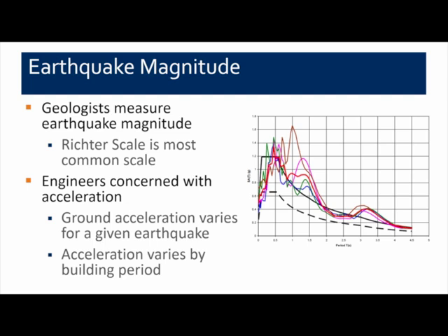Engineers, on the other hand, are more concerned with acceleration, and that's the rapid movement of the ground and thus the building. The ground accelerations vary for a given earthquake, depending on a lot of factors that we can talk about shortly. And the accelerations also vary by building period. And the building period is the time that it takes the building to sway back and forth one cycle.